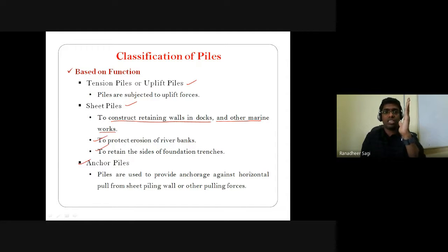So in such a case, to prevent the failure of the sheet pile, you can have some members driven into the ground through the sheet pile, so that these members act as anchors. Here we construct piles that act like an anchoring mechanism, which can minimize the horizontal displacements expected to develop in your structural elements or foundation elements that you are constructing in the field.